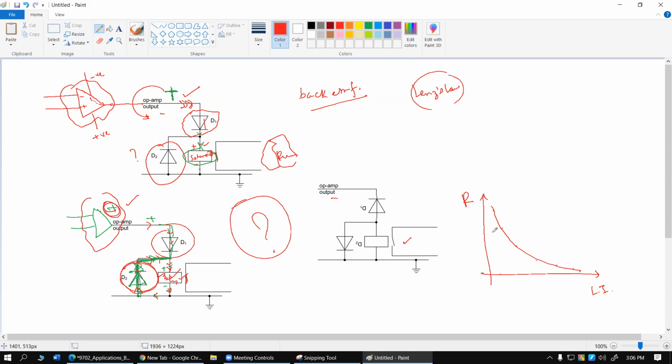totally makes sense. Now, once we have this curve, then we can use this curve to find out the resistance without using the ohm meter. Then directly by plotting some value of the light intensity, we can directly calculate resistance, or vice versa. Directly by measuring the resistance, we can directly calculate the relevant light intensity that we are trying to measure.